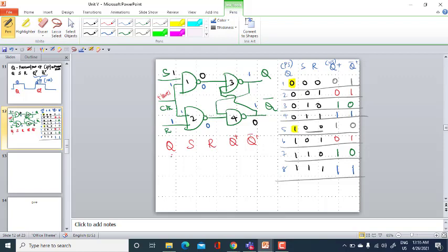So whenever we are using this SR flip-flop, ensure that this 1 and 1 combination should never occur, because this is said to be a not reliable state, otherwise an indeterminate state combination. Here this state is said to be the indeterminate state. This should not happen at all. Ensure that this should not happen.